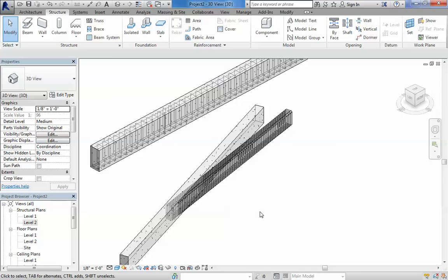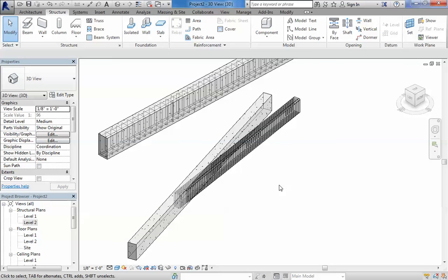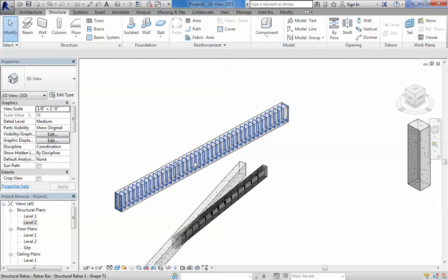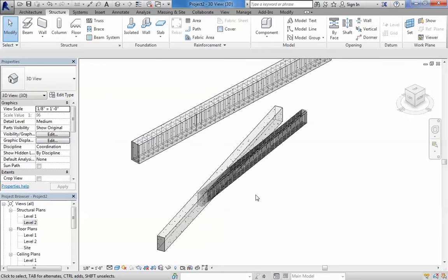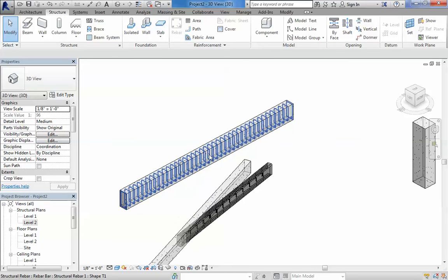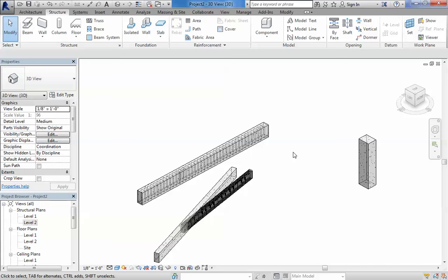So here's the problem. When I created the section of the beam, in the first one it was perfectly perpendicular to the beam, and in the second one it wasn't. The place you're placing your rebars is in that section plane, and then what it's doing is extruding itself according to the perpendicularity of that section. So the important thing is actually how you cut the beam in order to afterwards recreate those rebars on that cutting plane.